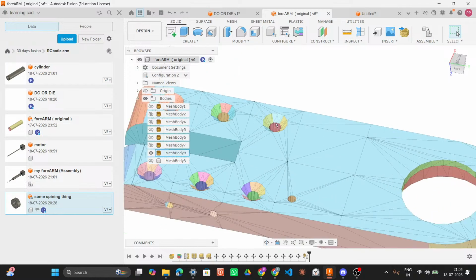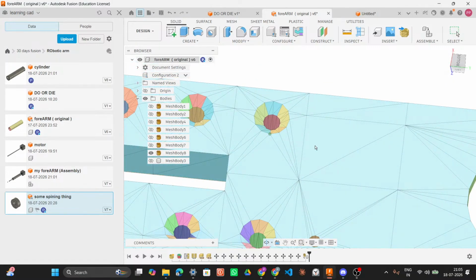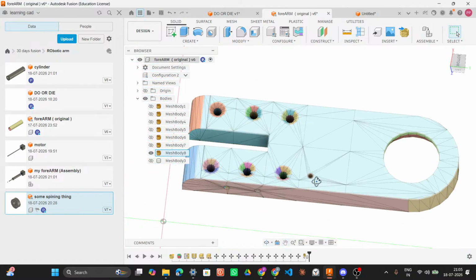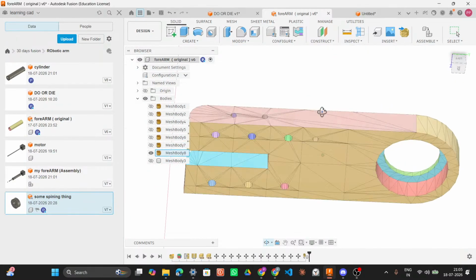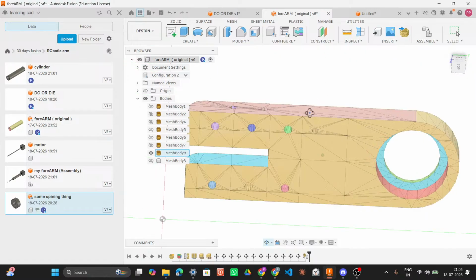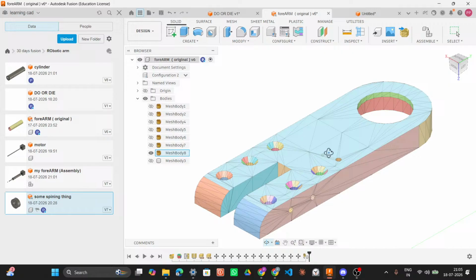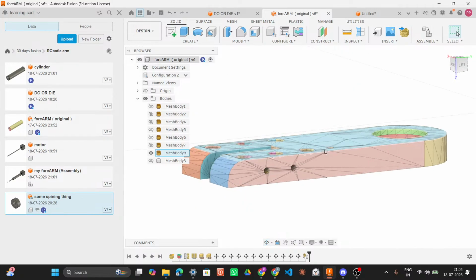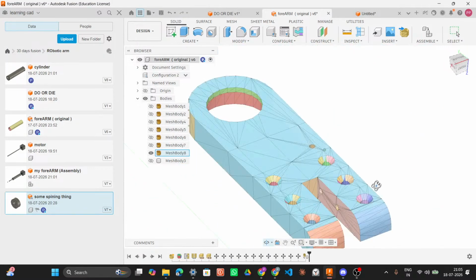Because you could get all of those holes and that bigger hole with the shoulder in it, extrude it all as one shape, and then do one sketch from the side to get the two holes going the other direction, and also get that radius.